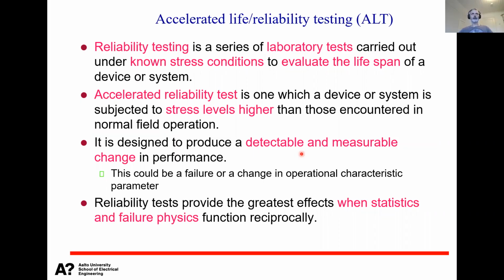So it's not only that the product explodes or smoke comes out, but you can somehow monitor the behavior, the functionality of the device under test during the testing. So for example, you can monitor how the resistance of an interconnection is changing as a function of testing time or something like that. So preferably it is some kind of an operational characteristic which you monitor.